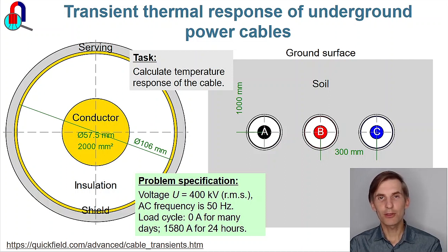transient thermal response of the underground power cables. This example is described in the IEC standard. The three-phase cables are laid in a flat formation underground. Initially, the cables are energized, but there is no electric current in the cables. The load is not connected.